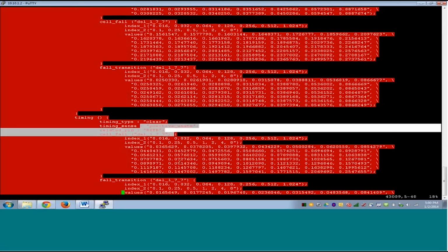So now what does a library have? Let's summarize. A library has a list of cells. For each cell, the function is defined, the input and output pins are defined, and timing is defined. The output pins will have the delay and transition numbers, the timing numbers. The input pins for combinational cells will have nothing, no timing numbers. For sequential cells, they will have setup and hold timing.